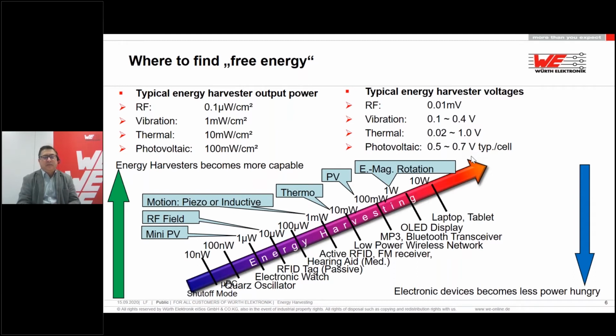By thermal, a standard TEG at 10 milliwatts per square centimeter is quite standard. I saw one company make a prototype with more like a 60 Kelvin temperature difference. They can reach 1 watt per square centimeter, which is quite enormous. Just imagine, if you have 1 watt per square centimeter, putting those TEGs on the cooling water of an atomic plant, you wouldn't need this big cooler to cool down the water for the turbines.